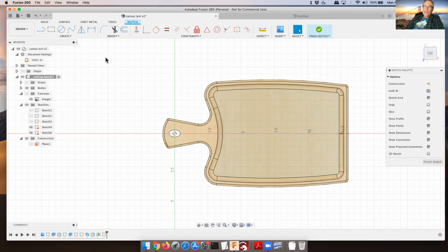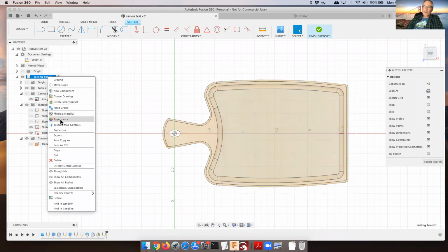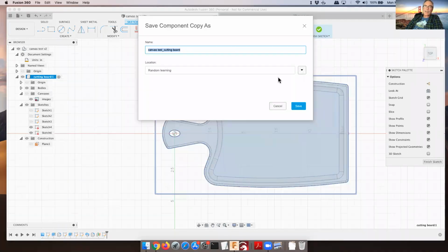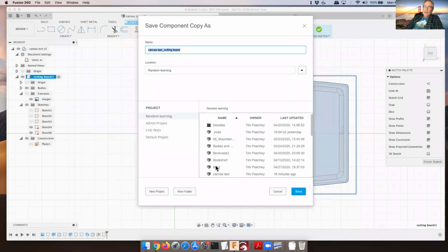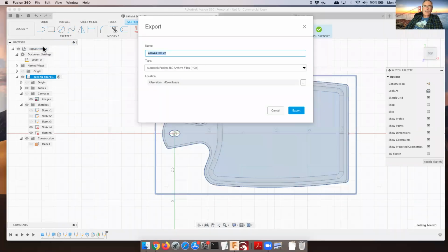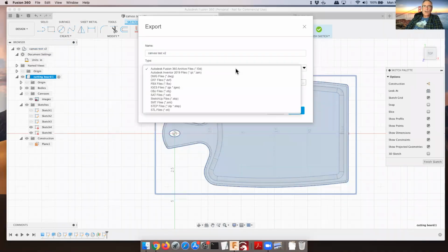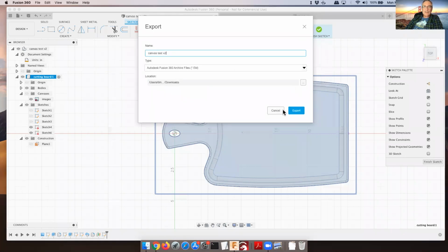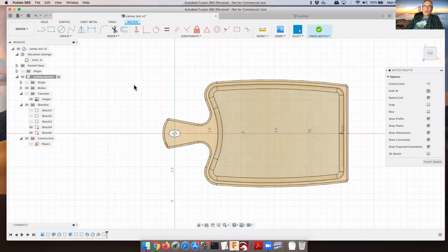So without derailing Tim too much, Shipoko, the CNC that we do training on, folks, for those of you who don't know, has the option of coming with software called Carbide Create. And Carbide Create will import, for instance, an SVG or a DXF. Those are two-dimensional drawings, which you then use inside of Carbide Create to define the rest of your project and then to assign tool paths. And it's out of there you generate your G-code.